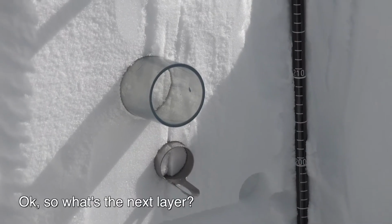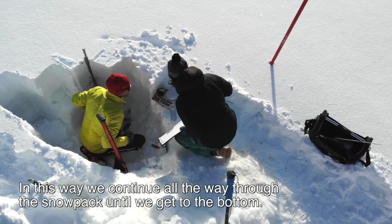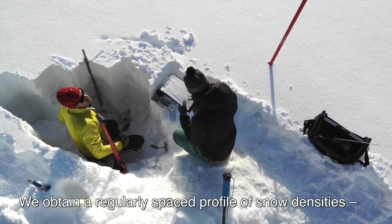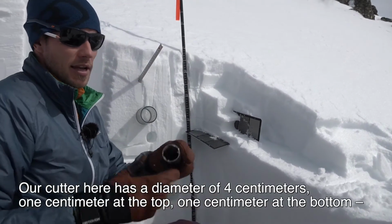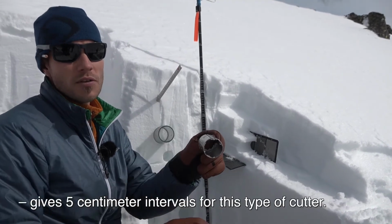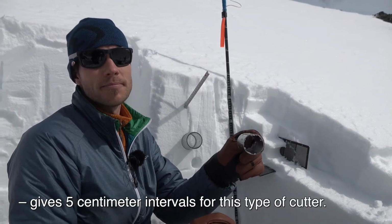Okay, so what's the next layer we're doing? Second layer. This way we continue all the way through the snowpack until we get to the bottom and we obtain a regularly spaced profile of snow densities with an interval of about 5 to 6 centimeters, depending on the size of your cutter. Our cutter here has a diameter of 4 centimeters, 1 centimeter at the top, 1 centimeter at the bottom, which gives 5 centimeter intervals for this type of cutter.